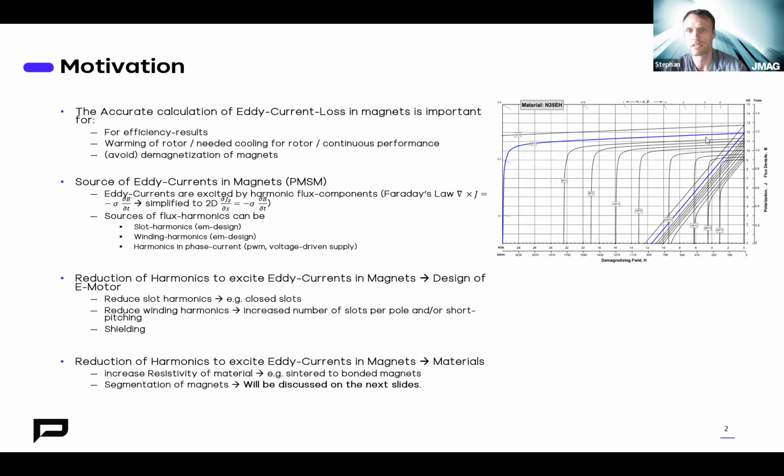The idea behind is that during the design phase, we need to simulate very accurately the temperature of the magnets that can occur during operation, to save the magnets from being demagnetized in some operating points or circumstances, like if we switch to active short circuit in the drivetrain of a vehicle. This might cause some irreversible demagnetization in the magnets, and this strongly depends on the temperature.